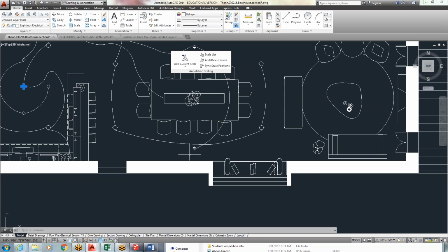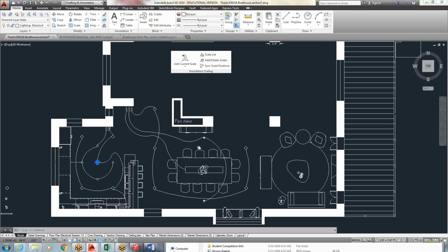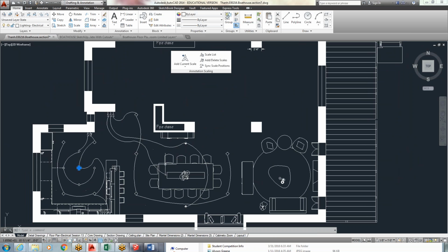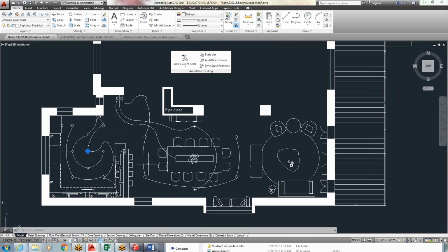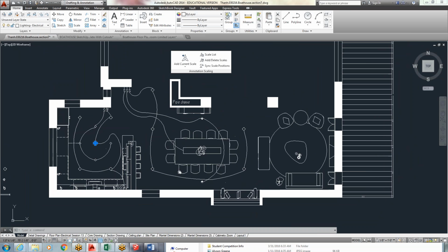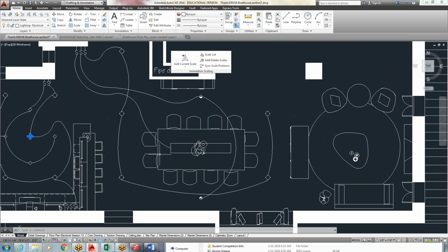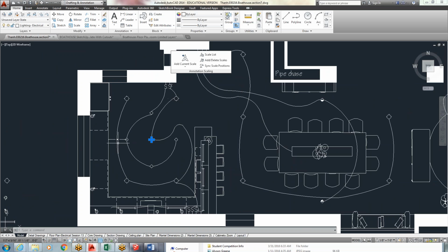So I added a wall washer here. I could have centered it more with the wall. I thought maybe it kind of captures some of the lighting into the reading area as well. But think about lighting besides just can lights. It gets very monotonous and boring in people's plans to see constantly can lights of one size. Do think about how these are very bright. They fill a lot of space. So if I want it more dim, I have a dimmer pendant in the middle, some wall washers, but some very bright 6-inch cans. And then I just had a couple 6-inch cans and a few very dim 4-inch cans.